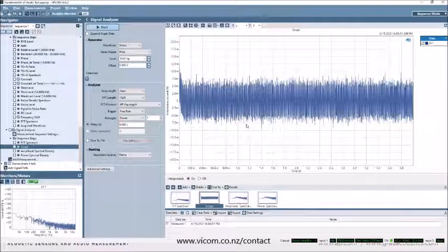Thank you, Dan. One final question here. Is the sweep continuously accelerating in rate from low to high frequency, or is it a constant rate from low to high frequency? That's an excellent question. It is accelerating, and that's what the log in log chirp refers to.